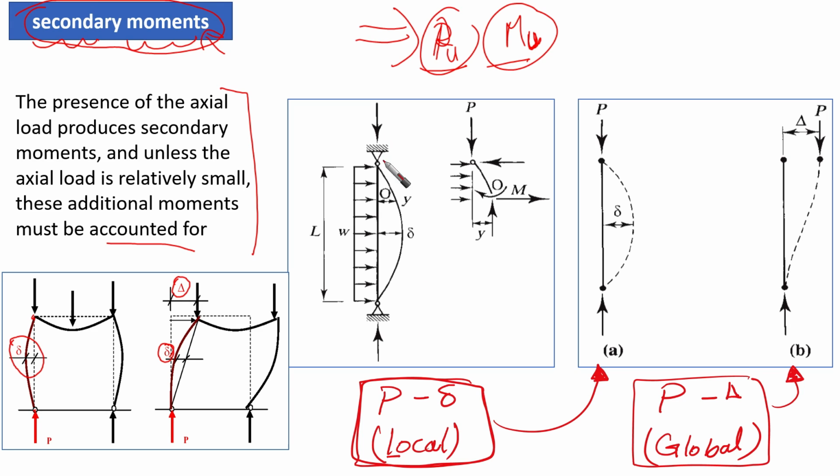And the behavior that is usually there is, if we have axial force, as you can see here, on a pin-pin condition element, and we have lateral loads, we found that the elastic line of this element is going to be displaced laterally, as you can see here. The maximum is going to be at the middle with small delta.